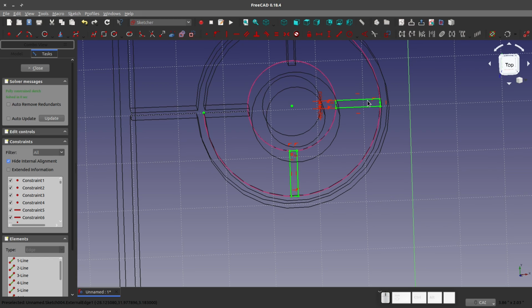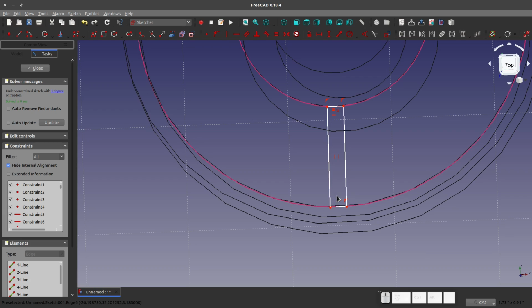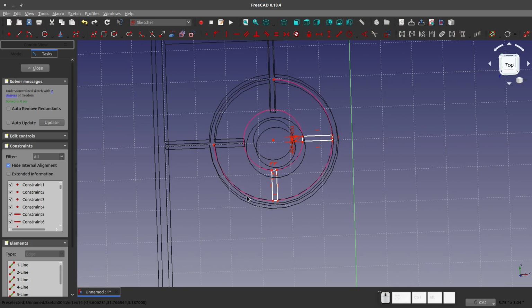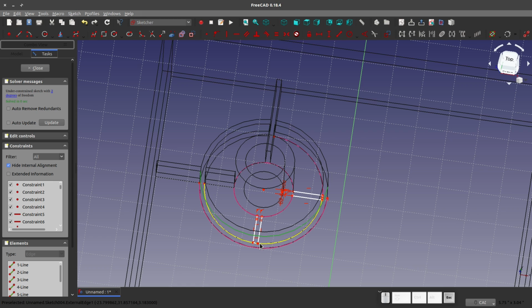There is one problem that I'm seeing. I need to get rid of this coincident. I'm going to leave a little gap the way that I have it constrained now. So I'll get rid of this, and let me import another edge here. So I'll make it coincident to this outside edge, which is much more effective. My mistake there.